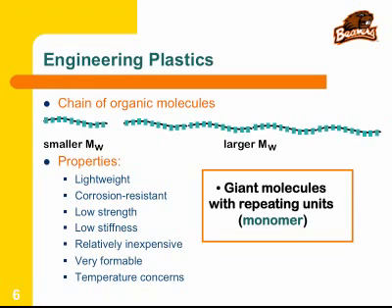The main thing is the temperature at which you can create a shape is a lot lower compared to the temperature required to create a shape out of metal or ceramic. And so that is the advantage of first using the polymer to create the shape. And once you have the shape that you want, right, at relatively lower temperatures and forces, you can get rid of the polymer and now you can fuse the particles together. Right? So energy efficiency is higher when you're working with this particular format. Okay.